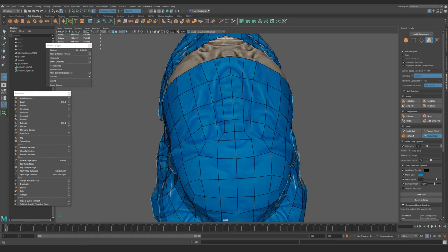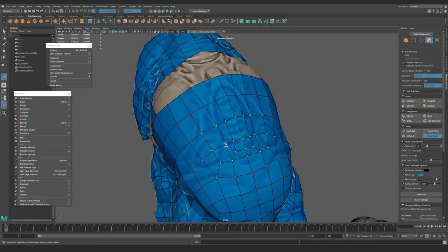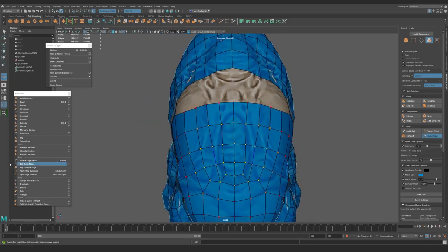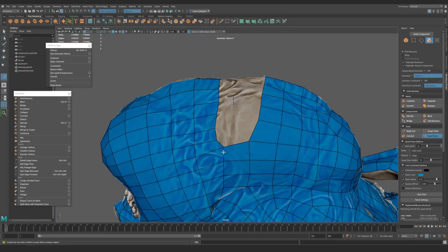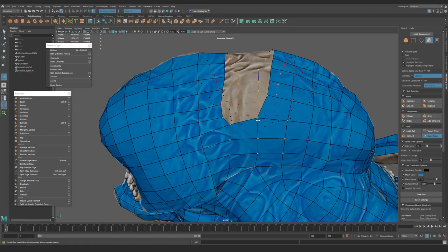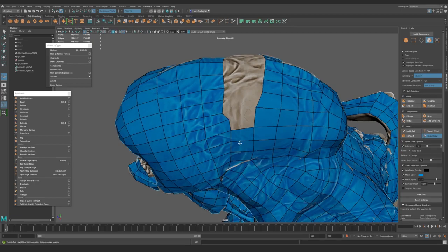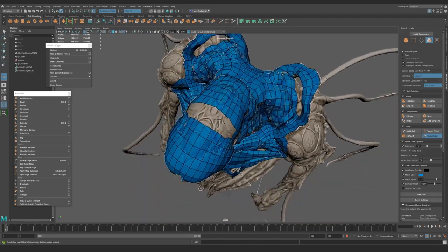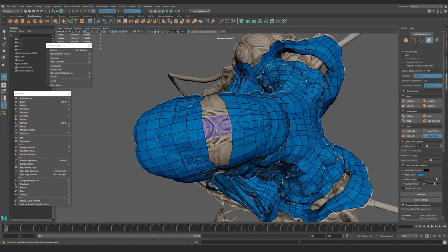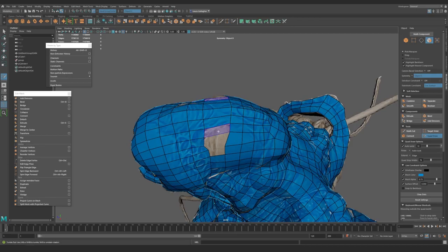These corner points are a great way to redirect a bunch of edge loops that you are adding, if you really want to keep everything as quads. As you can see, they really allow you to redirect loops that are coming over the head of the creature, around the head of the creature. And it allows us to have a bit more geometry towards the front of the creature and get rid of that geometry towards the back in a very elegant way without having to resort to triangles.